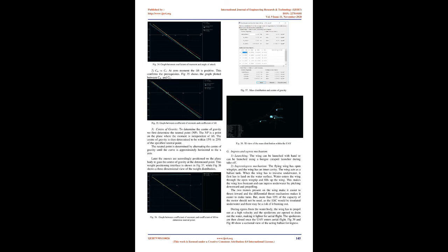Performing the analysis provides parameters such as coefficient of pressure, lift, induced drag, surface velocity, moment, viscous drag, downwash, and stream. From the above results we concentrate on the lift, drag, moment and lift-to-drag ratio. These parameters are then plotted against angle of attack and lift. The plotted graph helps us understand the wing's performance.